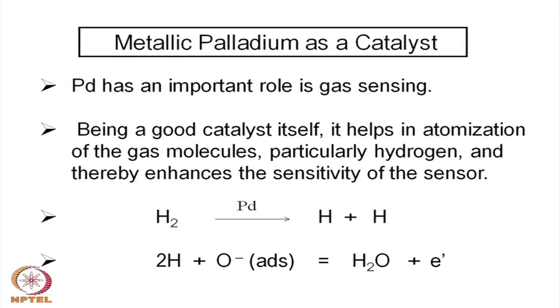Since adsorption is one of the major phenomena on the surface which gives rise to these kinds of changes in conductivity, there is a very important role of catalysis, because initially we have seen that first of all the oxygen molecule has to get atomized by a catalytic process, and then that oxygen atom picks up an electron. So, catalysis also has a very important role in determining the conductivity and also the adsorption in presence of some of the gases.